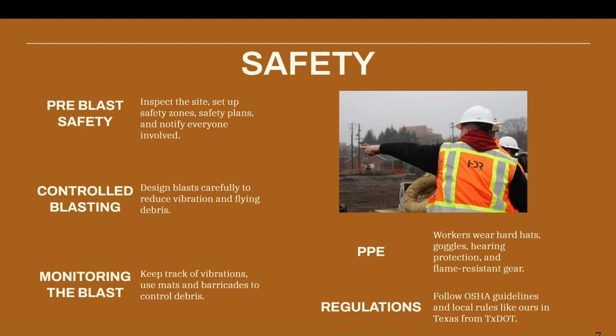Safety in blasting rock. First, we have pre-blast safety, which involves inspecting the site, setting up safety zones, safety plans, and notifying everyone involved. Controlled blasting: design blasts carefully to reduce vibration and flying debris.